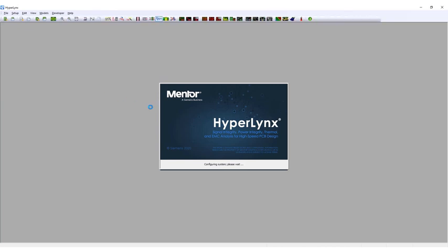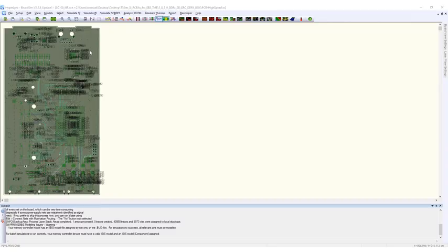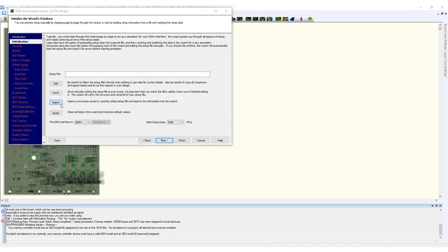To take that hurdle, the tight integration between Expedition and HyperLynx helps a lot. Of course, as an old and experienced layout designer, I am very happy that Rory, the SI expert, configured HyperLynx and the DDR-X wizard already correctly. Typical activities he did were checking and modifying IBIS models, assigning IBIS models, the configuration of power nets, and finally setting up the DDR-X wizard.